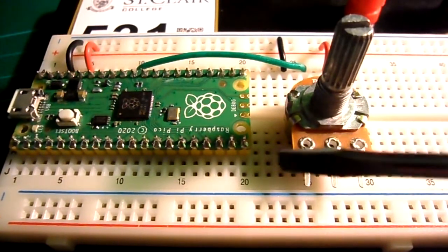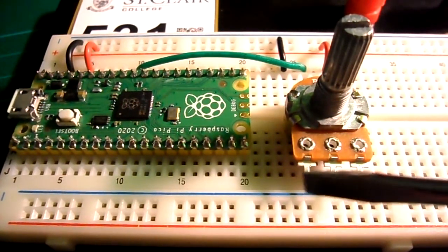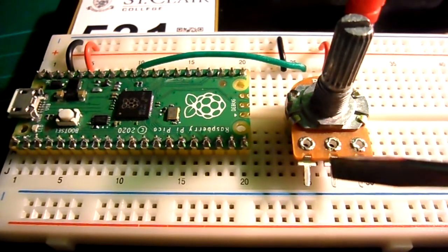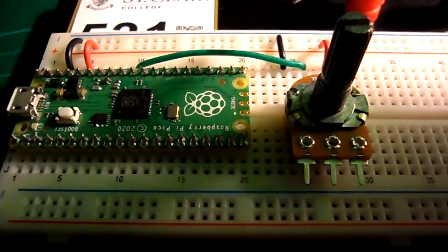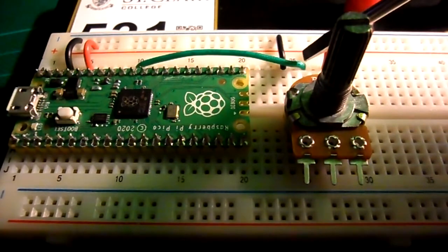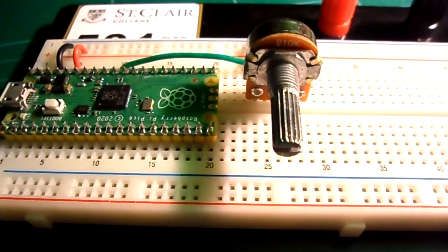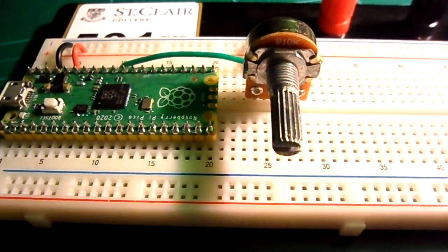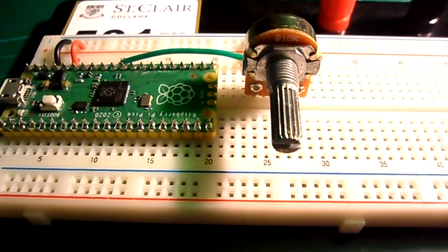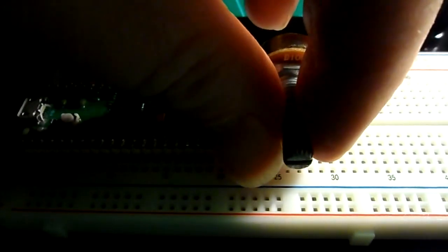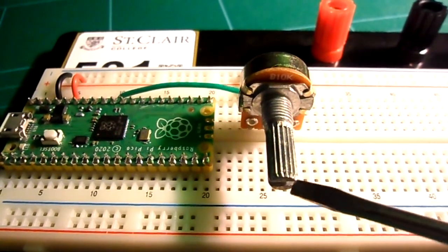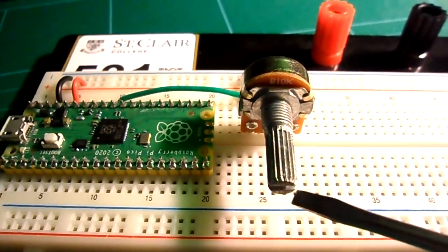So if you have a different style potentiometer, such as the one shown here, it still has 3 pins on it. The center pin is still the wiper pin, but the spacing is a little bit different from the small blue one that I just showed you. So you're going to need to space out your ground and your power 1 space further away from the center pin. And when you place it into your breadboard, we need to orient it so that the adjustment shaft is pointing down, and try to find a center position. So turning it fully counterclockwise versus turning it fully clockwise. So we can see about halfway should be about there. So you can see there's a little slot in there. So if you adjust it halfway, the slot should be horizontal to your board.